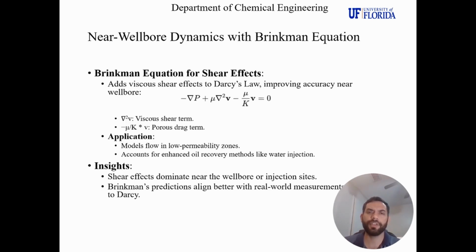So we have the near wellbore dynamics with the Brinkman equation. The Brinkman equation extends Darcy's law by including viscous shear effects. It's especially useful near the wellbore where the velocity gradients are high and viscosity plays a larger role. We have an equation here.